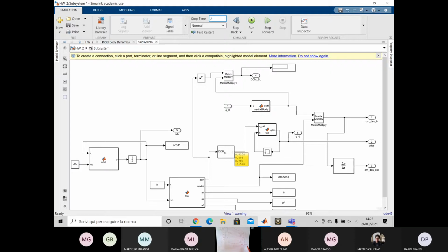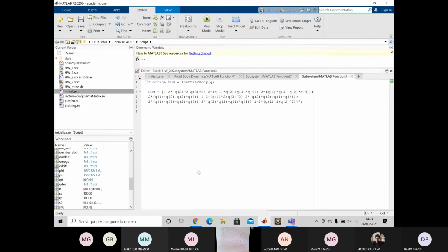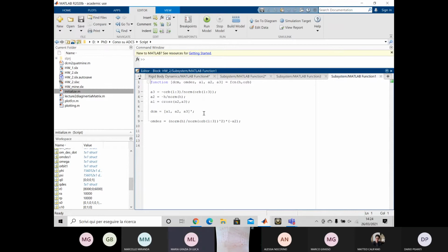Here inertial is LVLH. Yeah. Are you meaning LVLH? Because we have LVLH. Correct. Yeah, the LVLH is what I'm calling A here, but yeah. Okay. And so this matrix that goes from A to N is coming out of there. And so what I'm asking is, is that DCM going from LVLH to inertial, or vice versa? That's the first question to ask. DCM, it goes from inertial to LVLH, right?